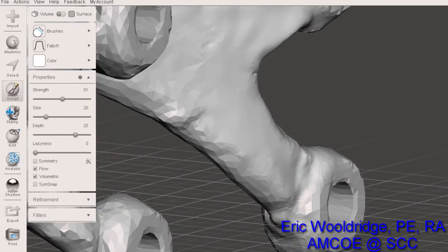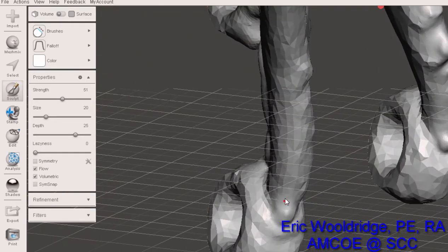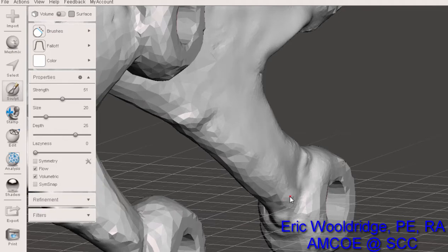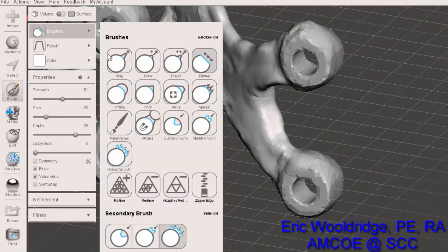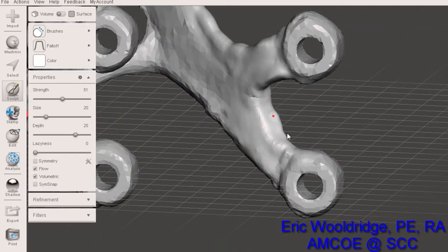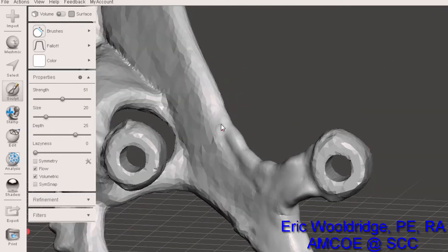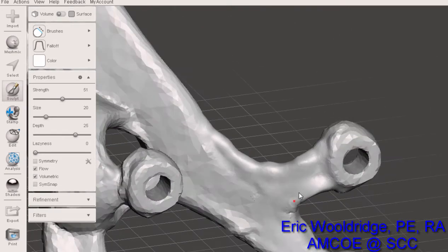So anyway, what you can do is you can go grab you an STL, some kind of generative design that you've created or have access to, and then pull it into Meshmixer, working with your brushes such as bubble inflate and flatten to thicken up zones where stress may be concentrated. Thin curved corner points always accumulate a lot of stress, and then use your flatten to kind of get rid of that effect. This rib that you see right here kind of forming itself, that's going to be pretty strong. Alright, so give it a shot. That's a quick little tutorial.